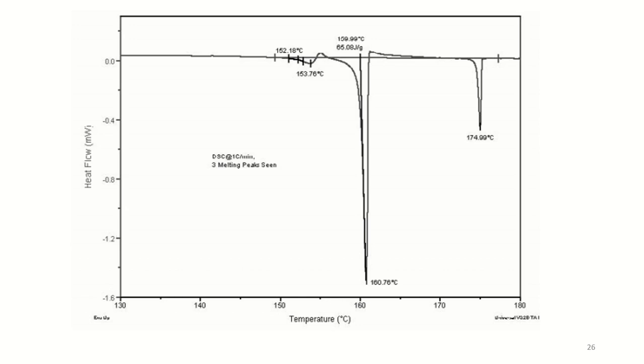Since this sample changes significantly with the lower heating rates, it is necessary to use higher heating rates, which may be 50 to 100 degrees Celsius per minute, to minimize the time and opportunity for one polymorphic form to convert to another polymorphic form.